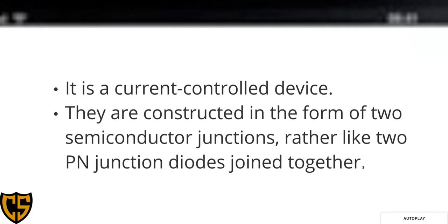Our transistor operates when we forward bias the emitter to base junction. The transistor can act as a switch, like an ordinary switch that turns on a light or a fan. Instead of turning on the device yourself, the transistor does it. But for it to activate, you must supply current to the base. The current you apply to the base is what controls and turns on the transistor.